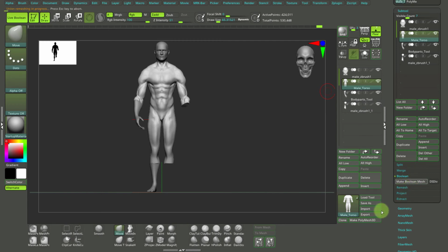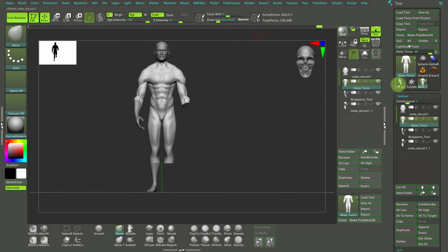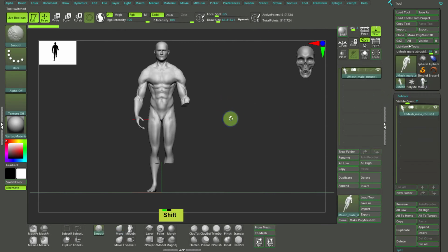Okay, so hit Boolean Mesh. And it will calculate things. In the top left row, you can see that union remeshing is in progress, and we have about 500,000 polygons now. So it will take some time, but it will be good. And as you see, it is done. So here's a U-mesh model now, U-mesh.